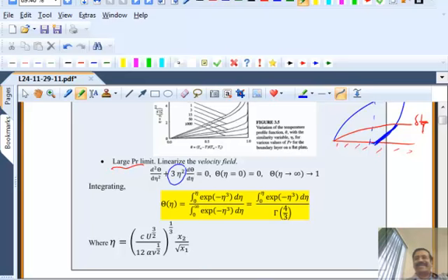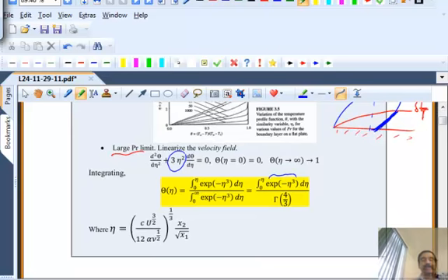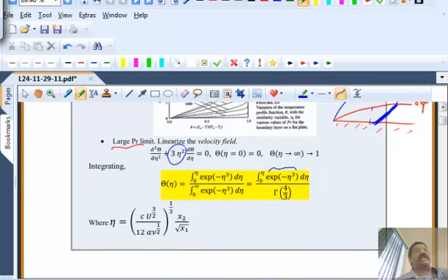So over the entire boundary layer thickness for the temperature, you can assume the velocity profile to be linear. And when you do that, you get a solution that doesn't require you to evaluate a quadrature in terms of f, but still requires you to evaluate this function, e to the power minus eta cubed d eta. There is no analytical integral for that. That has to be done numerically. Okay? That's where we stop. Now, are there any questions on that?